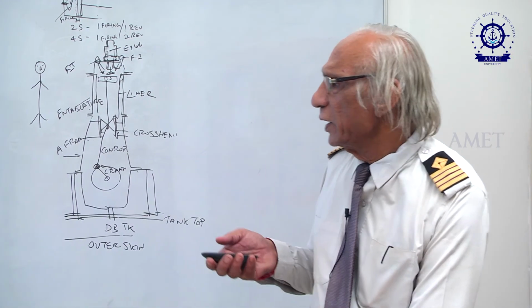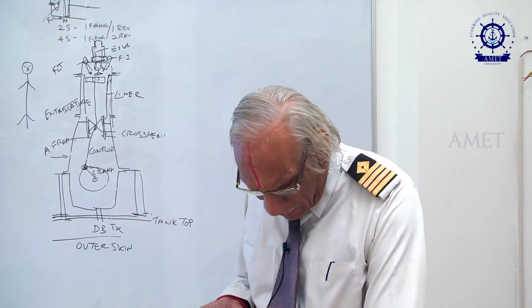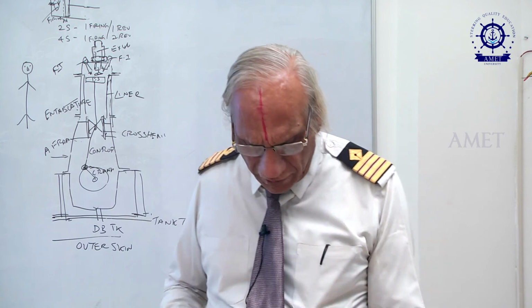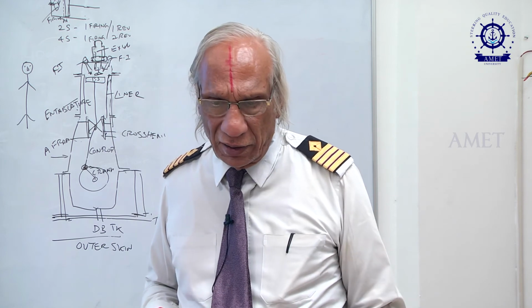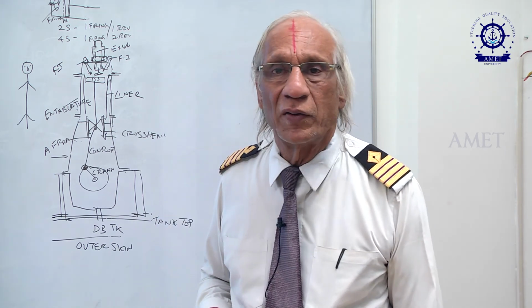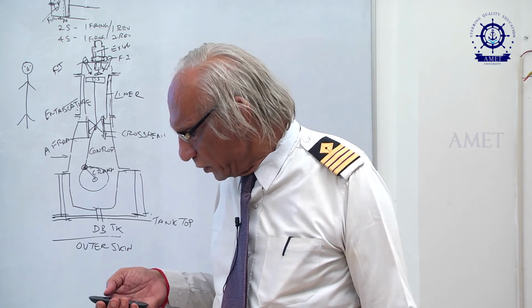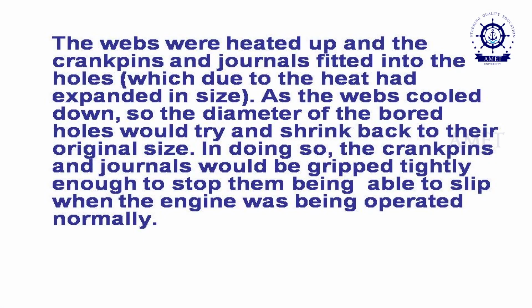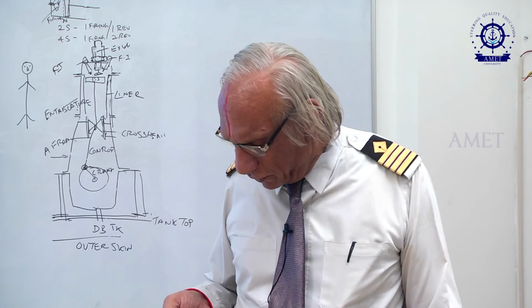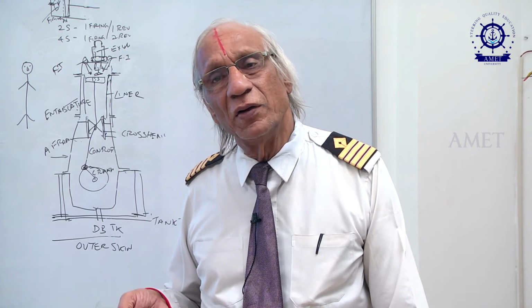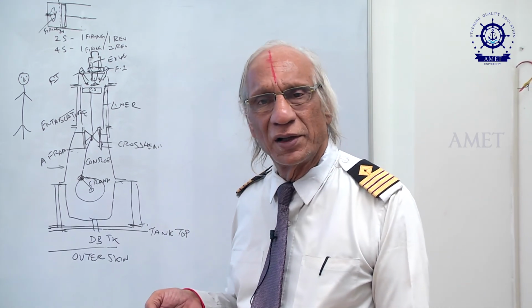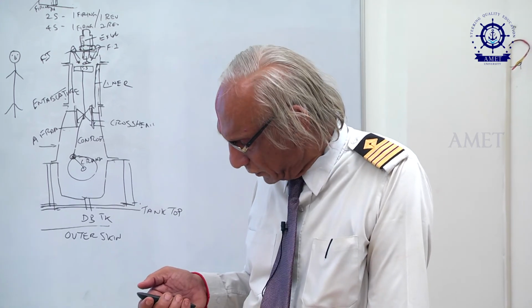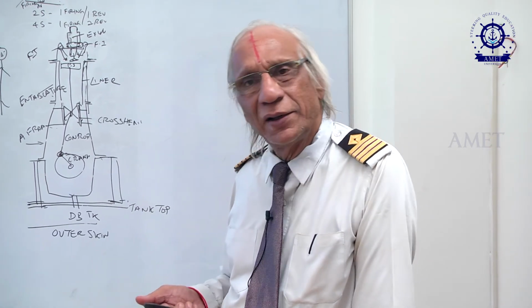So, after shrink fitting, you must make a reference mark so that at the next inspection, or whenever you do a frequent inspection, this reference point should be observed very closely, so that there is no slippage of the crank web around the crank journal. It is very important, because once a slippage takes place, the entire timing diagram of the engine will be affected. The engine will be affected because from the crankshaft, the drive is taken to the camshaft. The camshaft has all the timing gears, mostly the cams for operating the various other moving parts, which we are not discussing in this lecture. That will be covered in a separate lecture.